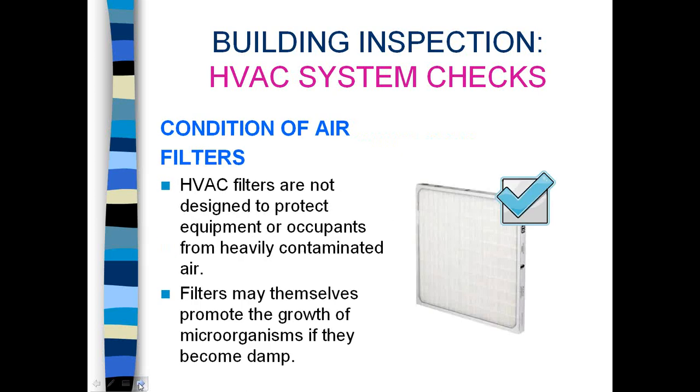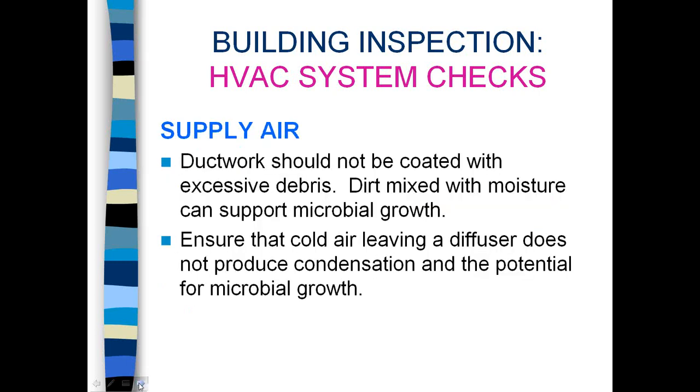The condition of the air filters is also critical. Filters may themselves promote the growth of microorganisms if they become wet. Finally, check the supply air. Ductwork should not be coated with excessive debris. Also ensure cold air leaving a diffuser does not produce condensation and the potential for microbial growth.